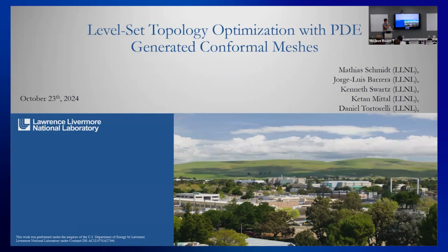So this presentation is about level-set topology optimization with PDE Generated Conformal Meshes. And the important part here is really, we wanted to develop on this project a topology optimization approach where everything can be done in a finite element framework, like for example, MFEM. So everything is basically PDE-based.